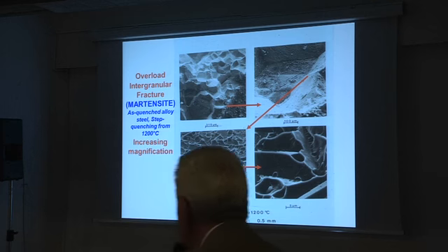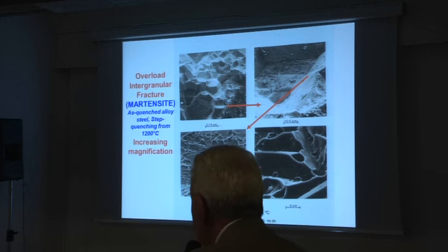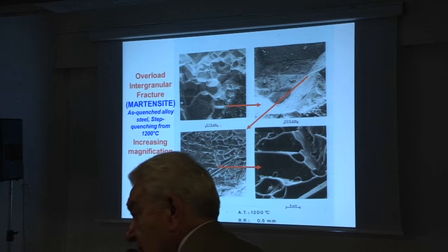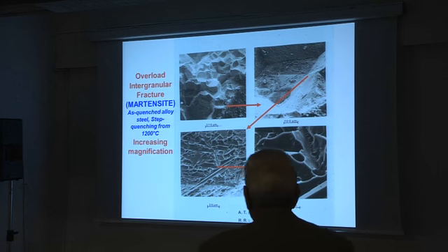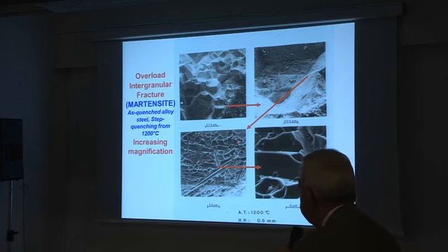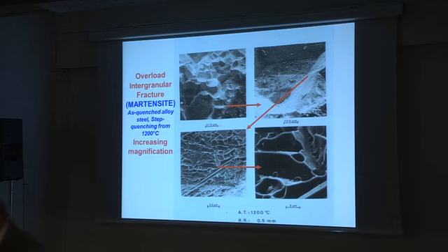And in the same steel, step quenched from 1200 degrees C with less stress concentration, you can have what is, an overload. So we are still speaking of overload, intergranular fracture, and the fracture is along the previous austenite crystals.